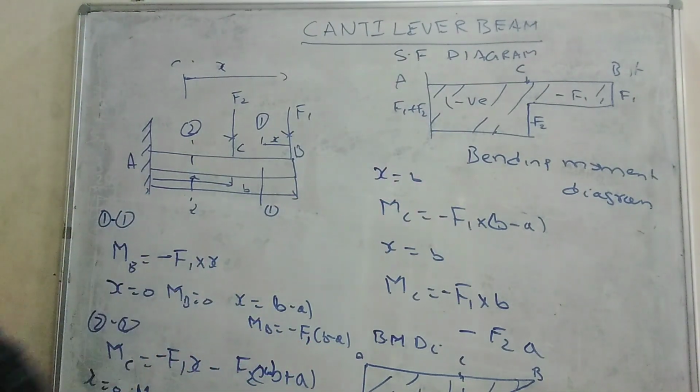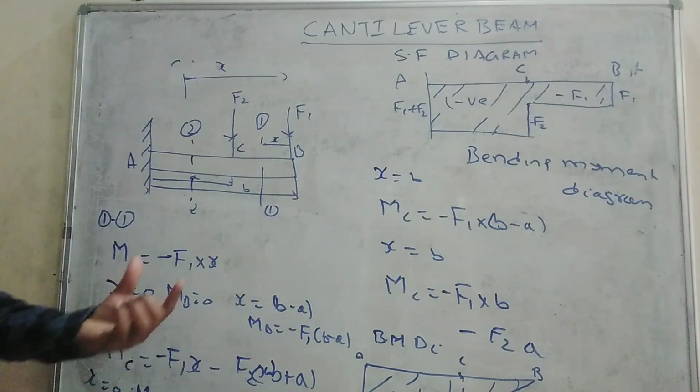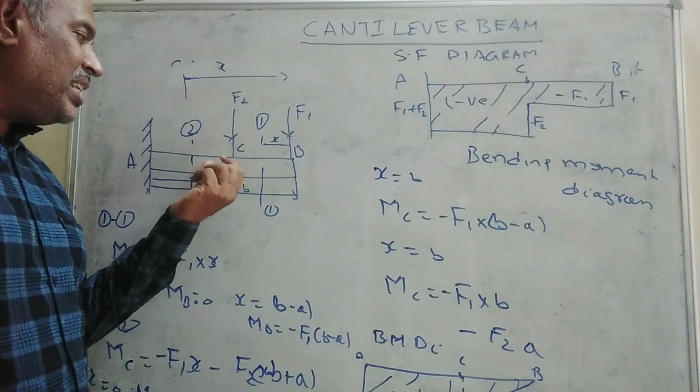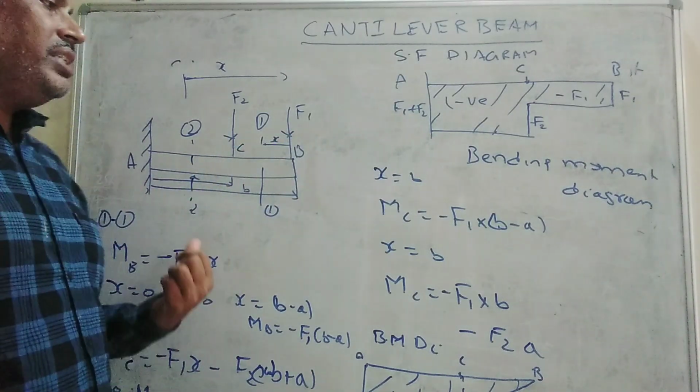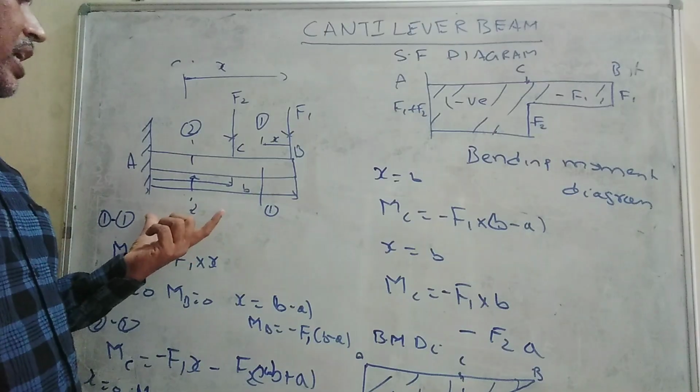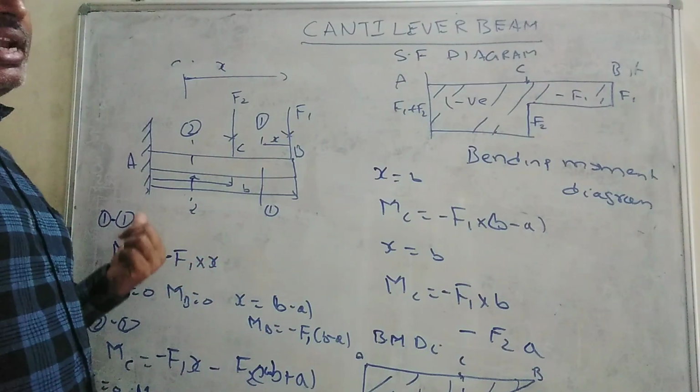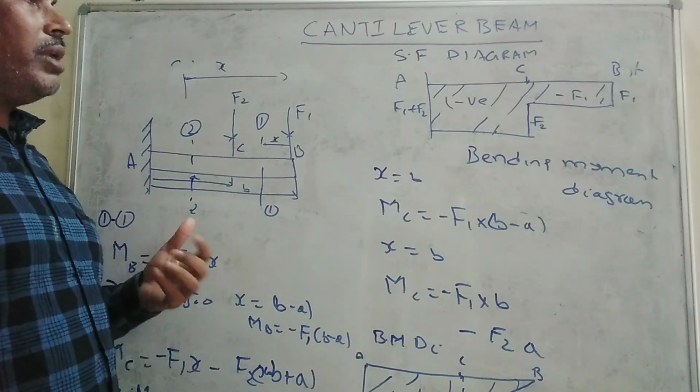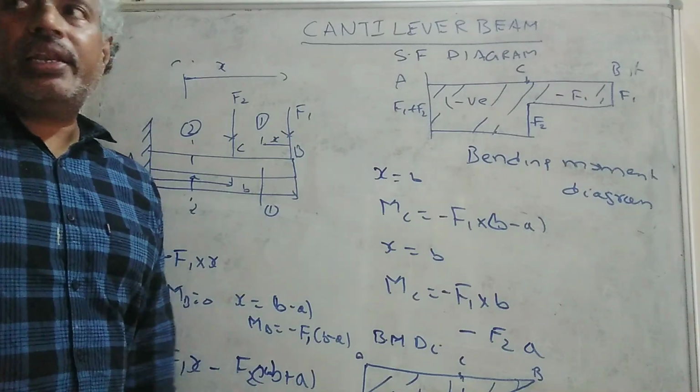Now the reason for drawing these diagrams is that we can determine the shear stress induced in a cantilever with the help of the shear force diagram, and we can determine the maximum bending moment and bending stress from the bending moment diagram, which is useful for the design of cantilevers.